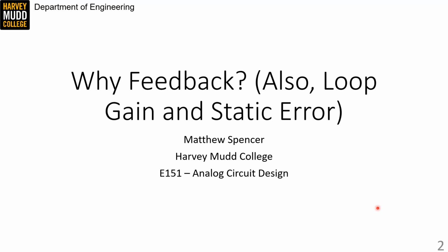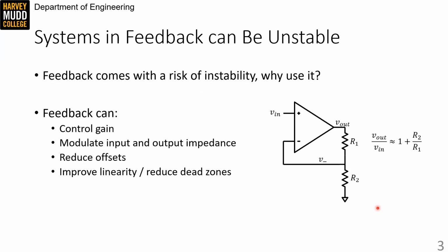feedback by listing its benefits, we're also going to define our basic vocabulary around feedback, which is surprisingly extensive. We're going to be talking about a lot of good things that can come out of feedback in this video, but it's crucial to acknowledge that feedback can cause instability. Anytime you commit to designing feedback into a system, you also need to commit to a thorough stability analysis.